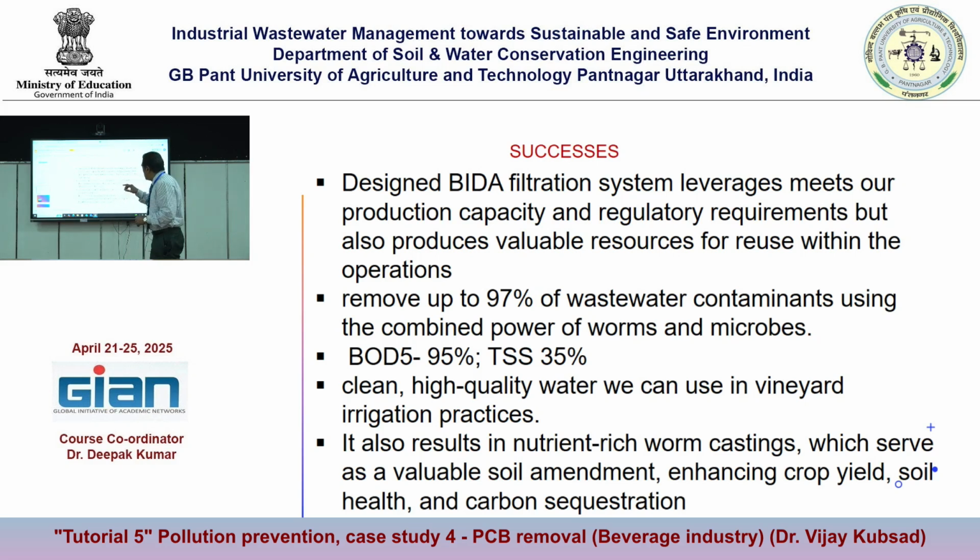So this is the same system. Contaminant removal is 97, BOD, and in addition to that, TSS and others are removed 30%, 40%. We are not bothered much about that because it is going to the receiving wastewater treatment plant. That will take care of it. But the major portion is removed. So this is the great success story, because the agreement is done based on the organic loading. So you are removing the major organic loading and contaminant both.